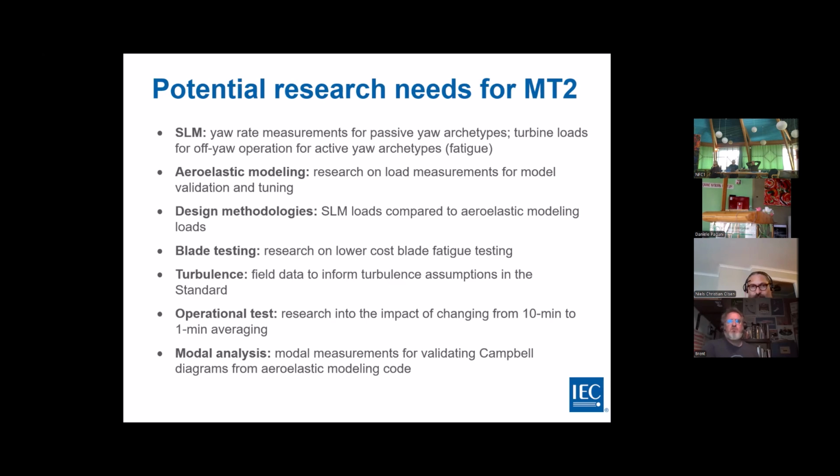As we look through the simplified load methodology, we also realize that it could be a significant fatigue load case for active yaw turbines that spend a good amount of their time running in an off yaw position. So we could benefit from some research and load measurements on those types of turbines. And on aeroelastic modeling, basic research on load measurements for model validation and tuning is always welcome. What do you need to measure besides power and RPM to really get an aeroelastic model tuned up and validated?